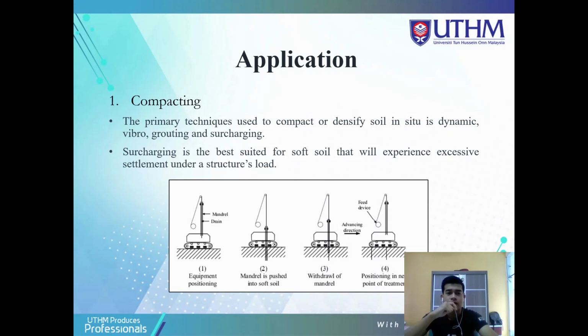Application for soft soil. The technique used to compact soil in situ is dynamic compaction, vibro-grouting, and surcharging. Surcharging is best suited for soft soil that will experience excessive settlement under a structural load. This method places soil fill on site to pre-consolidate existing soil prior to construction, and it helps to improve soil via compression, increasing stiffness and shear strength.